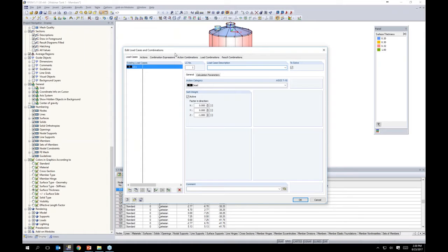I won't even apply external loads such as wind or seismic today. I do hope to do a future webinar on a structure such as this to really get into much more detailed analysis of the wind loads on this structure. So we'll just keep this as general fill pressures from the inside as well as self-weight. So the first one will simply be dead load, where we'll be activating this self-weight here, and that will be the only load that we apply for this particular load case.